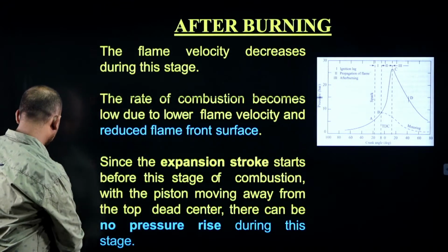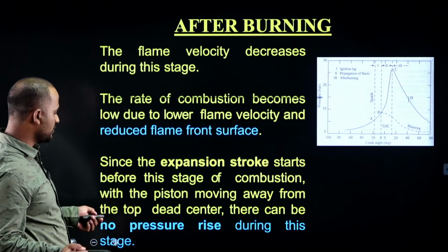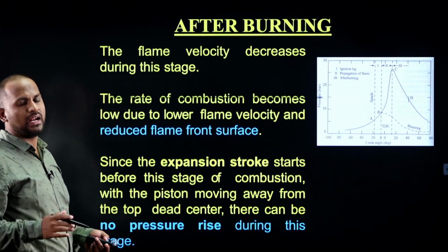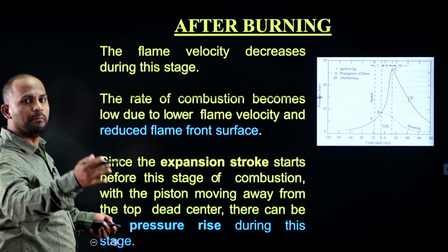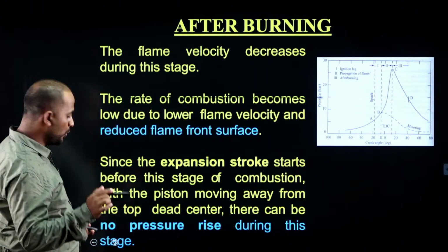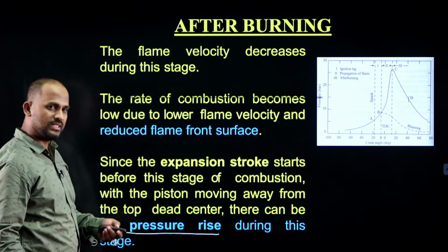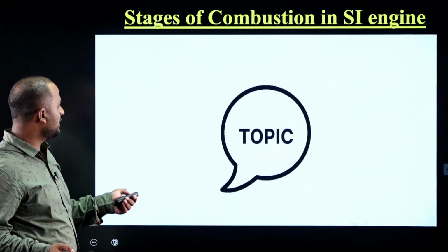So in the after combustion stage, lesser unburned fuel particles will be left in the cylinder, and the piston will be moving towards the BDC during the expansion stroke, which leads to no pressure rise during this stage. And that's why it is called the after burning stage.